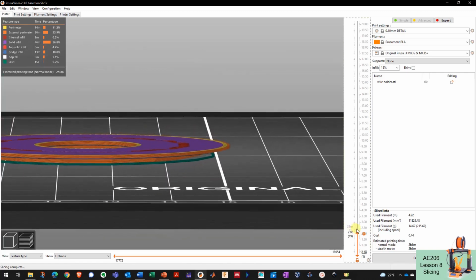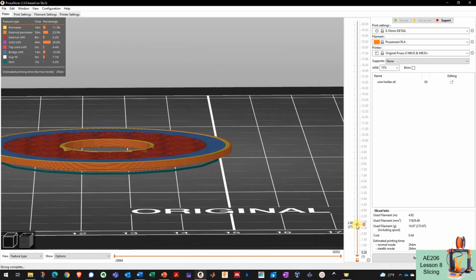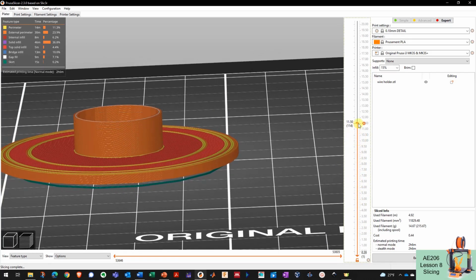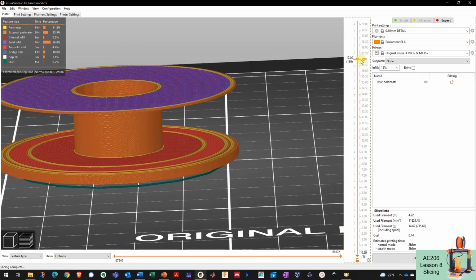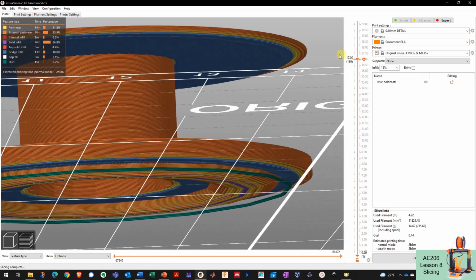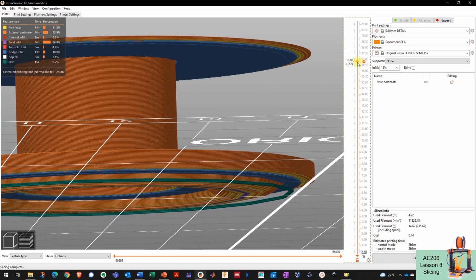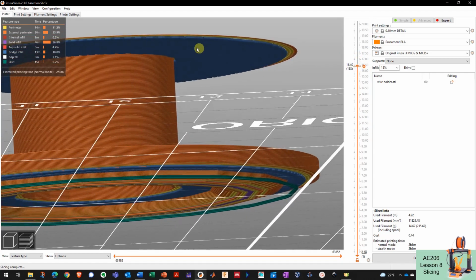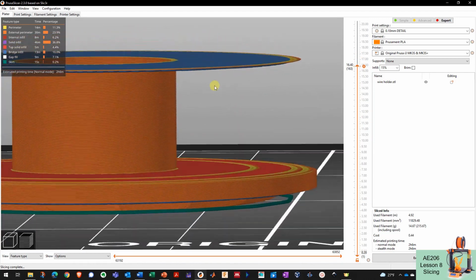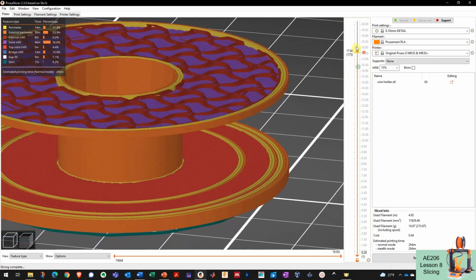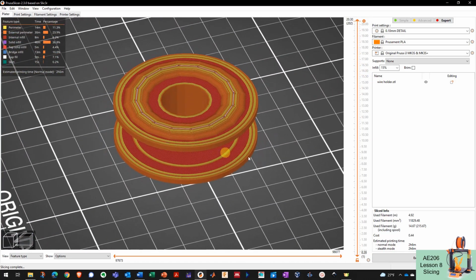Okay. But continuing on in the layer heights, as I come up, I start to get into the center of the spool, and then again I'll reach the top of the spool, and again I have another 90-degree overhang here, and the printer's coloring it that color because it's detecting an overhang. And again, the slicing software is saying the printer can't just print over thin air, so all of this plastic it oozes out here is just going to fall down, and it's not going to be a successful print. Okay. But that's the slicing for this orientation.